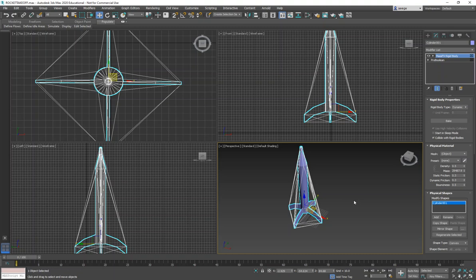After assigning the dynamic rigid body, it becomes one of the properties of your solid model. It instantly learned the mass, and there's a default value. At the same time, the vertical command menu on the right-hand side started showing me different values.